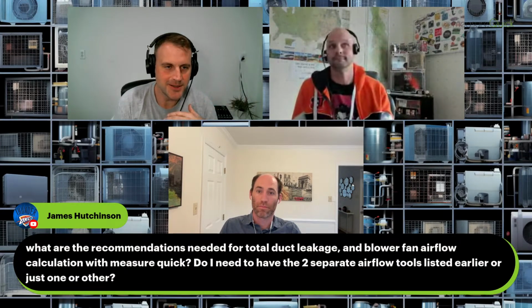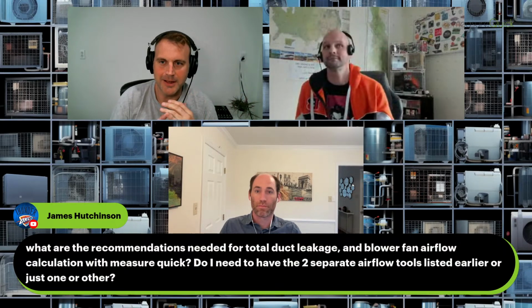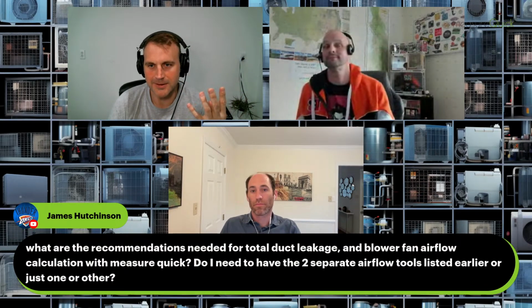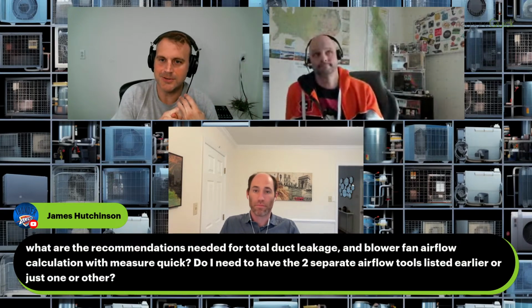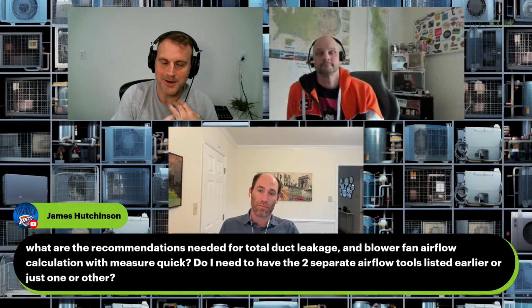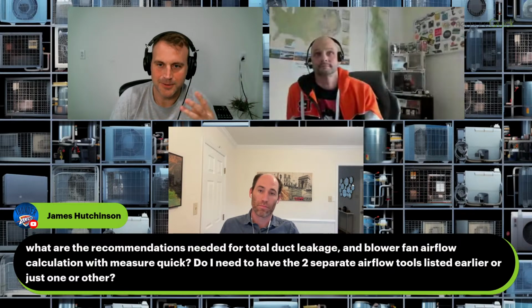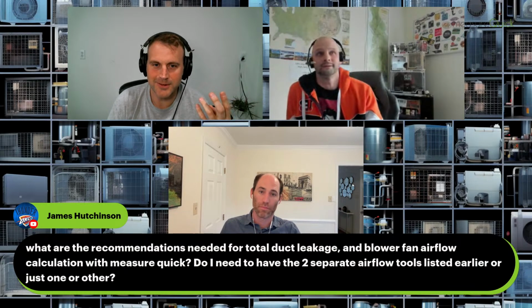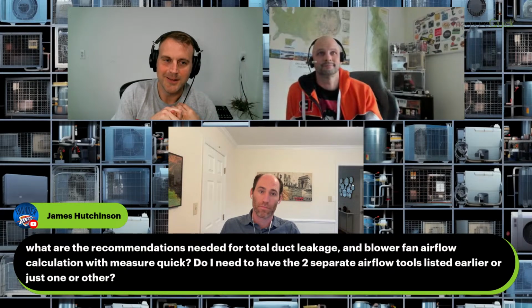So I'm just going to jump out there and throw this out: if you're following ANSI standards, ANSI has 4 methods they approve, right? Total external static pressure, or external static pressure, whatever you want to call it, a TrueFlow, a flow hood, and pressure matching. 3 out of the 4 of those are volumetric airflow. There's probably a reason they were hell-bent on that, right? So what I'm trying to get at is, I'm not saying don't do TESP, right?